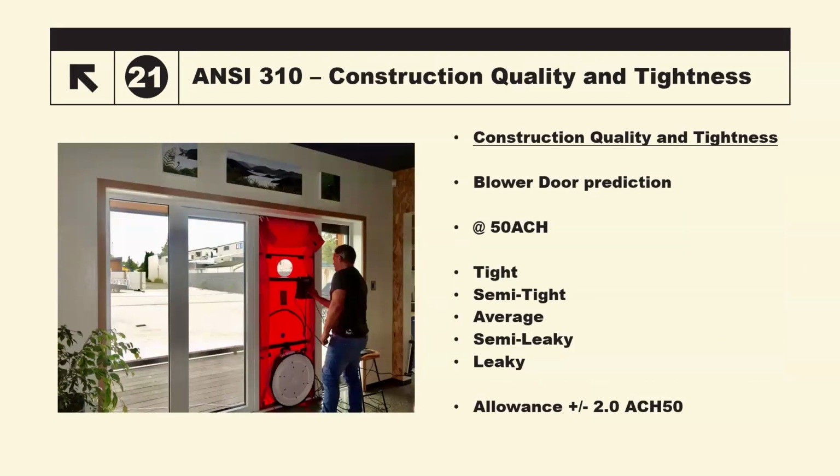And then of course, we'll bring this up. This is not a step in the system, but I like to bring this up because it's good to discuss it every time. When you're looking at Manual J, Manual S, you're looking at load calcs. Someone's got to put in predictive blower door results in order to get Manual Js to come out correctly.